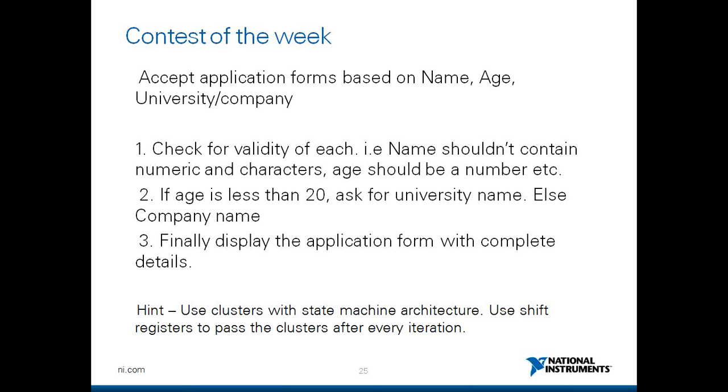And do use shift registers to pass the clusters after every iteration. And like we discussed today, use the bundle and unbundle operations to extract the elements of name, age, and university under different conditions in your state machine architecture. So this is the first contest, and those of you who are comfortable can go on to do this.